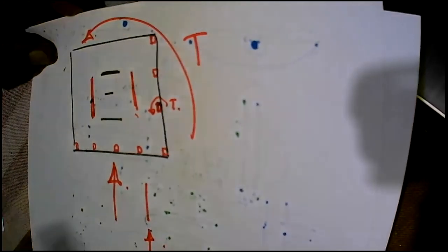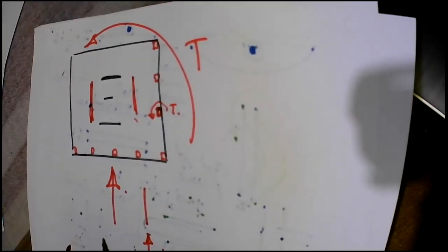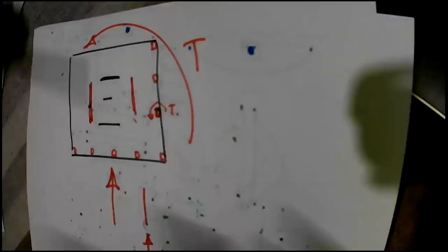So what actually happens is this twisting moment is now resisted by a couple of forces. There is a twisting moment, so this acts this way. So it will be resisted by two loads like this acting at an eccentricity x, with a lever arm x. So that's what happened. So basically what you see is, although the full building is subjected to torsion, it is resisted as lateral loads acting on two or more shear walls.